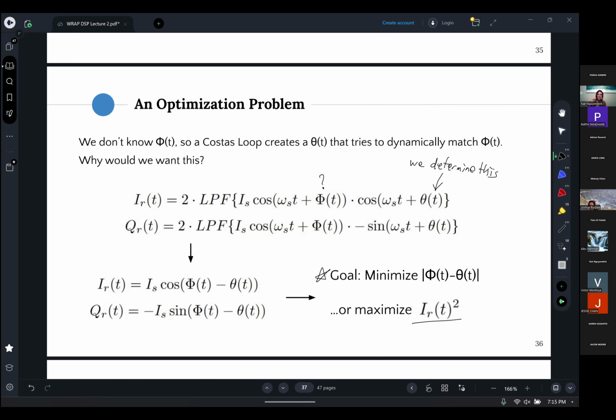We're going to utilize the Q component in the upcoming algorithm, but in terms of the actual communication and whether we're utilizing the Q component for sending data, that might be one of the options to extend WRAP in Spring, by evolving from BPSK to QPSK, actually using the Q component to send data more efficiently. But as of the WRAP system right now and for the assignments, we will be sticking with BPSK as we hammer in these last few concepts.